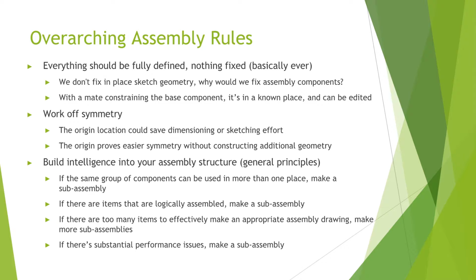So the number one thing that I try to preach and communicate is do not let anything ever be fixed. The reason being, if you have a fixed component in your assembly, where is it? Nobody knows. Right where you fixed it, right? But from an intentionality standpoint, where is it? Nobody knows. It's just there. Now, it might be on the origin. If you click the little green checkbox instead of in the graphics view, it might not be.